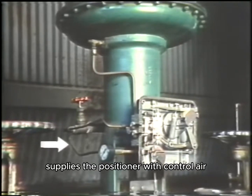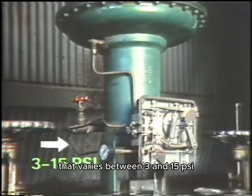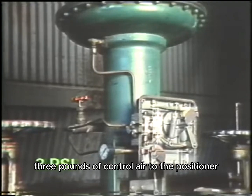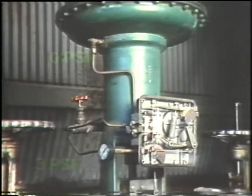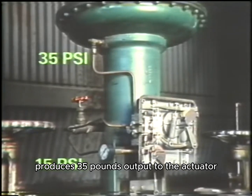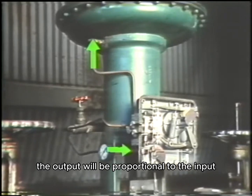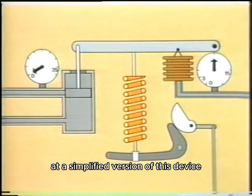This third line supplies the positioner with control air that varies between 3 and 15 psi to operate the positioner. 3 pounds of control air to the positioner produces 0 pounds of output to the actuator. 15 pounds of control air to the positioner produces 35 pounds output to the actuator. At every value in between, the output will be proportional to the input. To see just how a typical positioner does the job, let's take a look at a simplified version of this device.